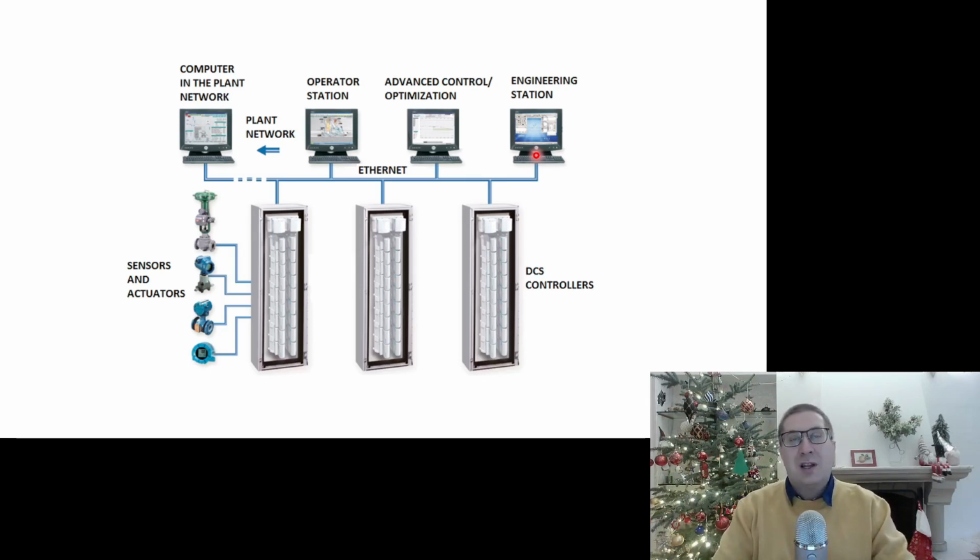So first, if we know that our AI algorithm will decide about which pump should be running and what should be the load of each pump, we have to create such process points like pump 1 load by AI method, pump 2 load by AI method, because the AI algorithm will write into those points. And one of the PCs that are connected to the network can be utilized for the AI method. So the AI algorithm will be executed on this computer.